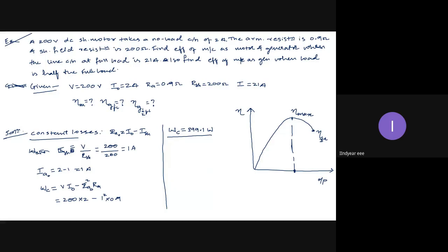Suppose a distribution transformer has to be installed in a locality where the load is around 500 kilowatts. I don't install a 500 kilowatt transformer there. I install at least a 700 to 750 kilowatt transformer, so that if the load increases in future, the transformer is in a position to take that load, because transformers cannot be replaced frequently.